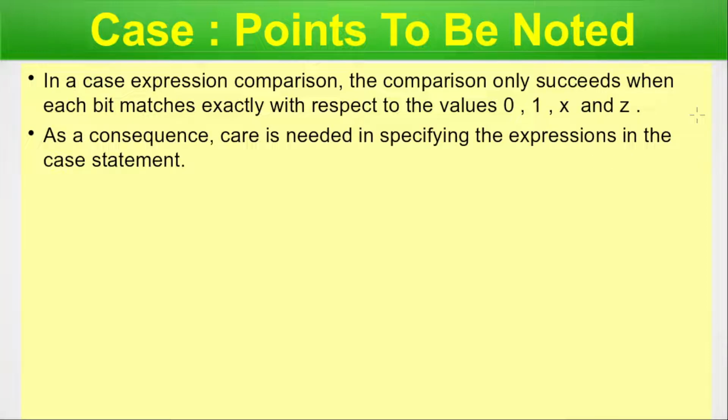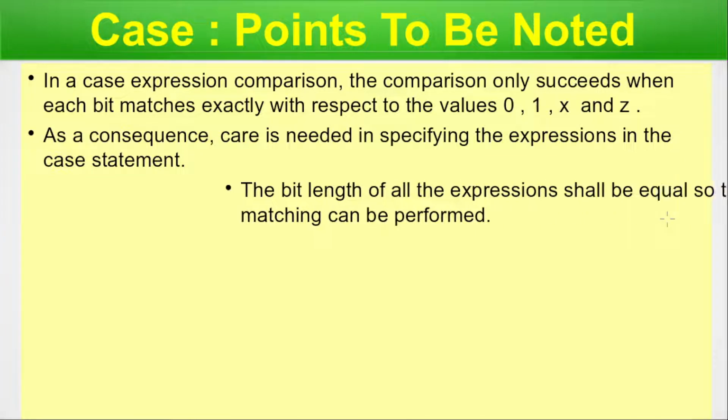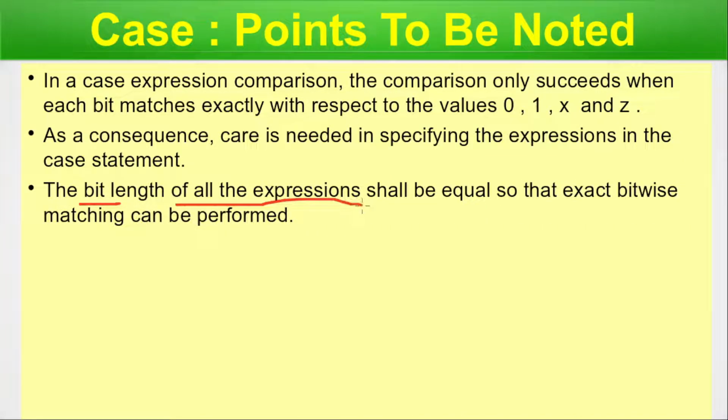Next, as a consequence, care is needed in specifying expressions in the case statement. When you are using the statement, you must be very careful. The bit length of all the expressions shall be equal so that exact bitwise matching can be performed. That is, when we have an expression or a variable, the bit length, from the LSB to the MSB, how many bits are there, is very important, and it should be matching throughout the code.